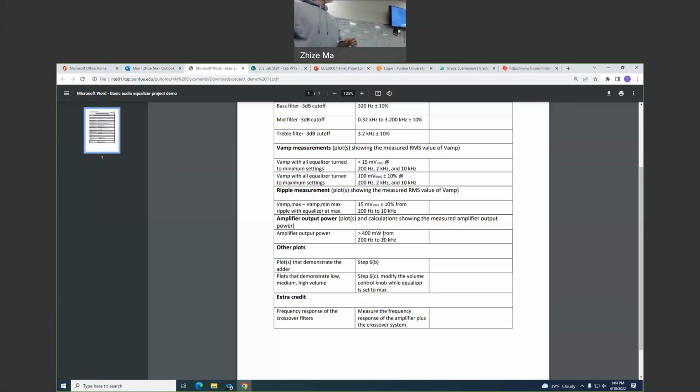Ben and Adam, do you have anything to add on this? I think that's, yeah. My biggest thing is, again, Aaron already touched on it, but make sure that when they're building and testing things, have them build one small sub-circuit, test and verify, build the next small sub-circuit, test and verify, combine, test and verify.